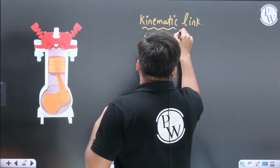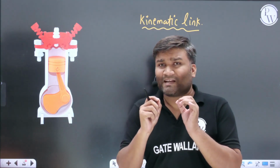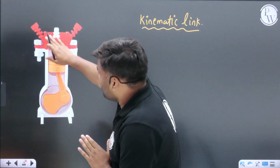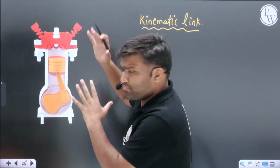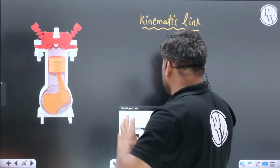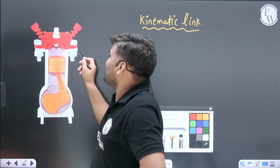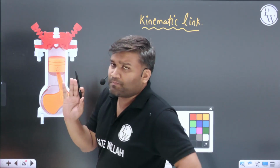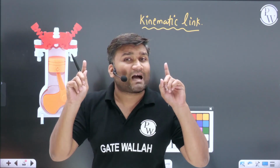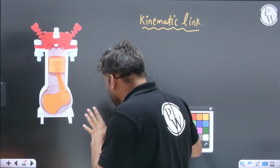By definition, a kinematic link is every small part of the machine or mechanism which is going to have relative motion with respect to some other part. Look here at this IC engine. In this IC engine, how many parts can you see? I'm not asking you to count the nuts and screws. I am asking you to count all those parts which have some relative motion with respect to some other part in this particular mechanism. Let's have a look.